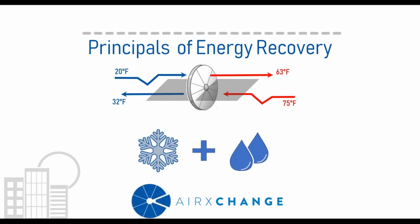So what does it take to generate frost on an energy recovery wheel? Well, you really need two things. You need the temperature to be at or below freezing. And if you look at these temperatures to the left over here, I'm going to highlight them. You can see that they are definitely at or below freezing.